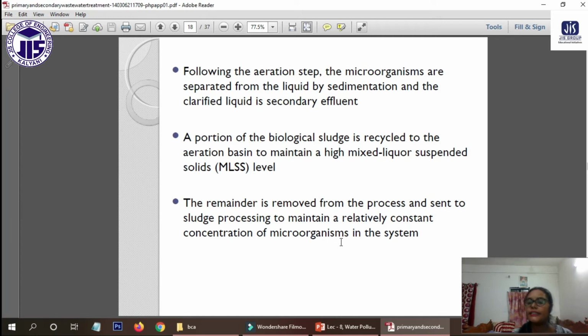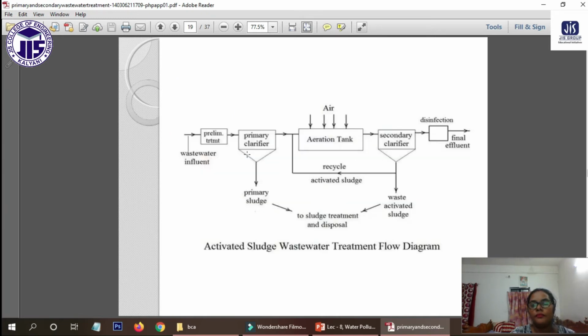Generally, what will happen is, a large tank, a large pond will be there, and from outside we are adding some microorganisms so that the reaction will be completed, and the system will be open. While there will be a deficiency of dissolved oxygen, the aerial oxygen from the air will come into the water to complete the reaction. So this is the total overall. After the reaction, whatever undesired product forms will be precipitated at the bottom, and after that we will take out that precipitation, and after processing we can use it as a fertilizer. That is why it's called the activated sludge process. So these are some of the steps of the activated sludge process.